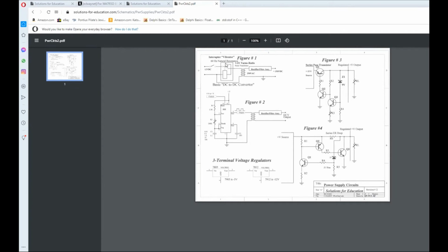What it really was is this: it had contact and break contact, back and forth in here. As soon as you turn it on, you can't get DC through a transformer, you'll burn up the transformer. However, this guy would buzz back and forth, make and break contact, and guess what you've got? Pulsating DC going through the primary, which shows up in the secondary as your 250 volts.